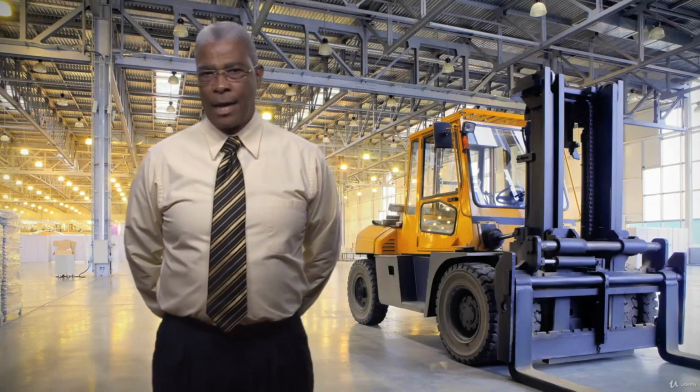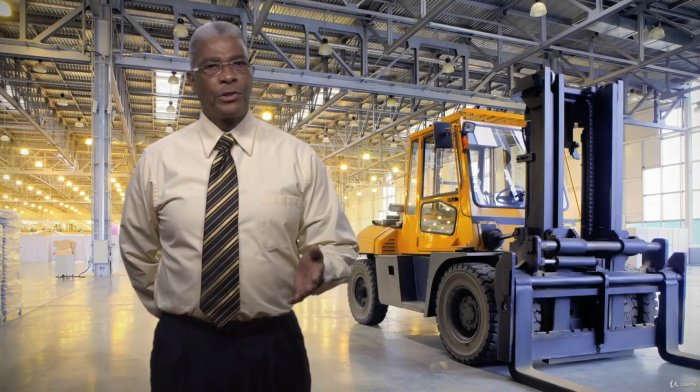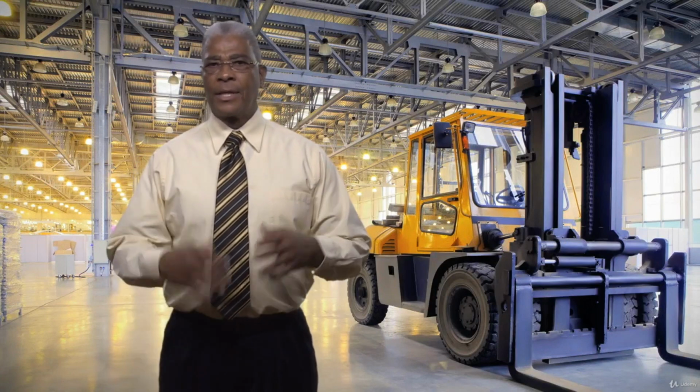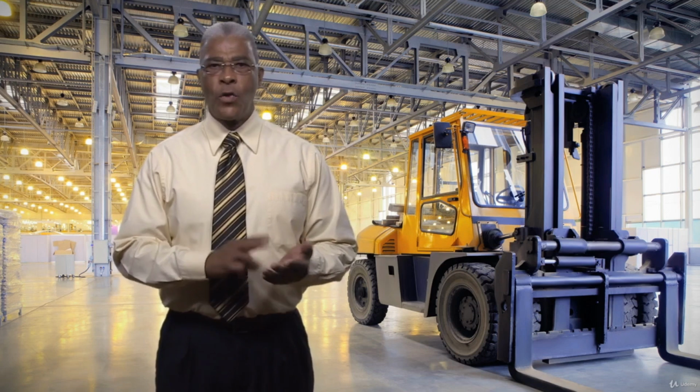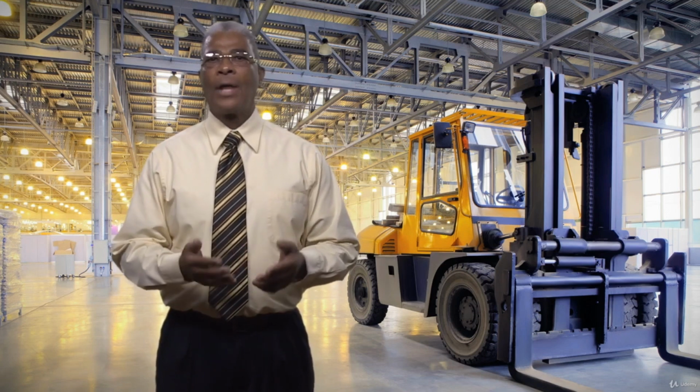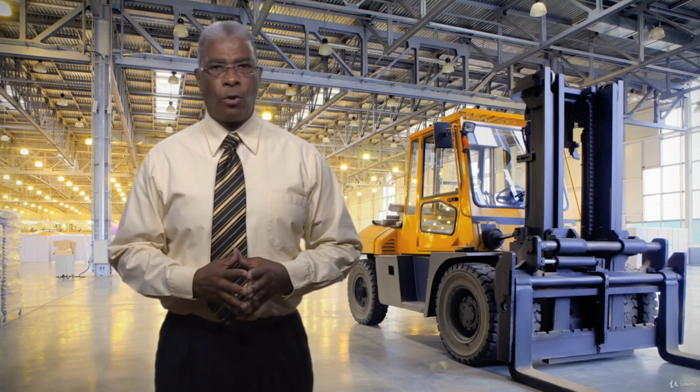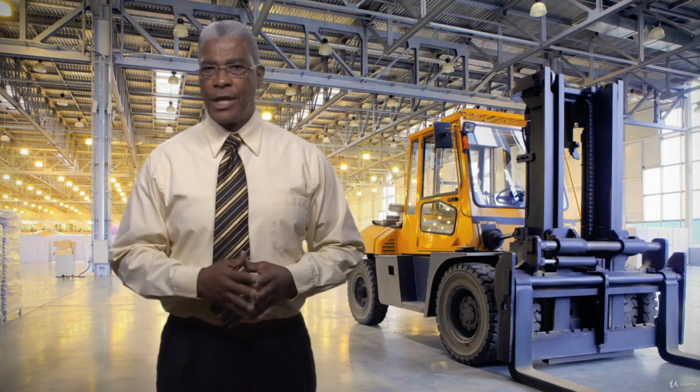Implement electrical lockout-tagout procedures in coordination with appropriate procedures for safely isolating other energy systems. Some examples are hydraulic, pneumatic, thermal, process gases and fluids, chemical, and mechanical. This procedure must provide for the isolation of all energy sources that could endanger employees.